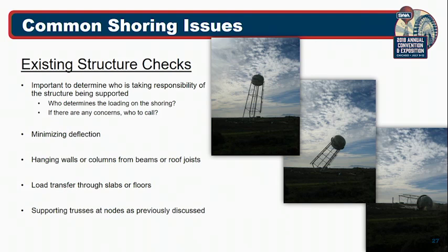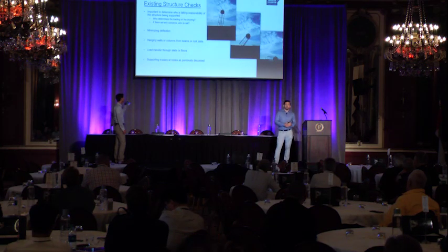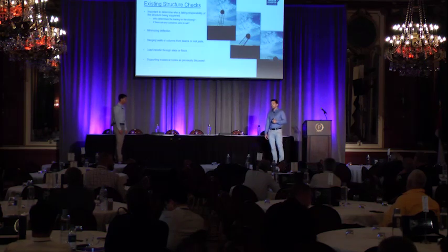So, existing structure checks. The reason this is important to you guys is it really comes down to understanding who's taking responsibility for the structure. As a scaffold contractor or installer, typically you want to be responsible for the system that you install and make sure that it's strong enough to support the loads it was designed to support. However, determining whether or not the structure can be picked up at that specific location definitely should be discussed up front with your contractor, your client.